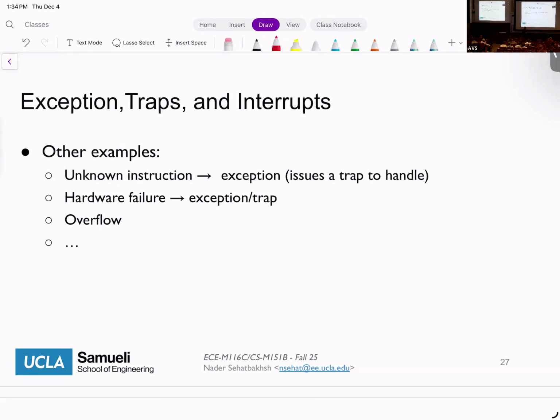Modules have a communication system, and like one bit is off, just because that can happen. Is that something that would... Yeah, one bit can be off as well. Usually we have error corrections to fix that, but if the error is detected but we cannot fix it, either we dump that packet and redo it. That's usually what happens. But yeah, if something happens along the way, you might actually, again, crash and restart the whole system.